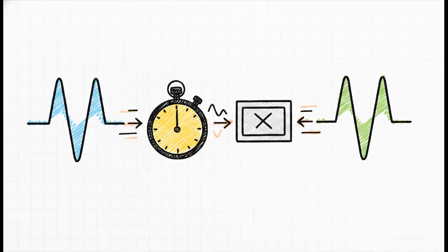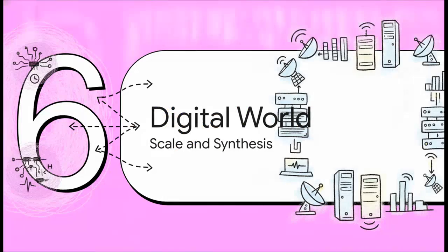And that brings us to speed, or what we call propagation delay. The inverter is incredibly fast, yes, but we still can't break the laws of physics. It takes a tiny, finite amount of time for a signal to push in, trigger the transistors, and actually change the output. We measure this in two ways, high to low time and low to high time. The average of these tiny fractions of a nanosecond dictates the absolute maximum speed, or clock frequency, at which your processor can actually run.